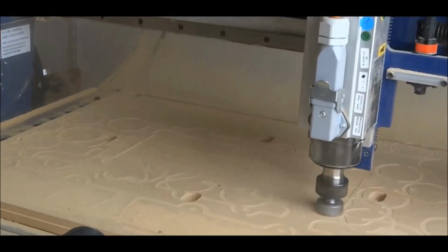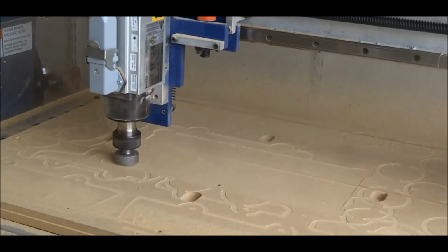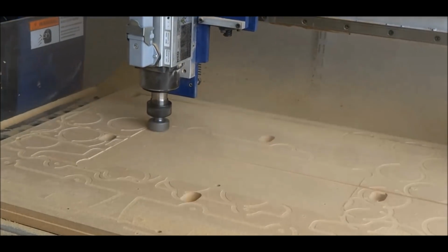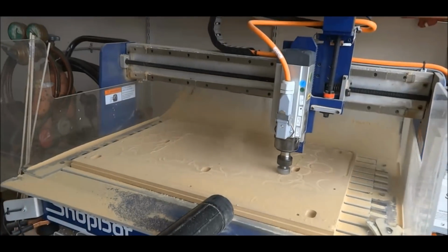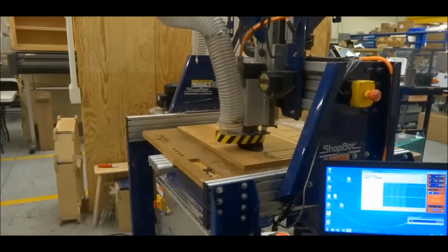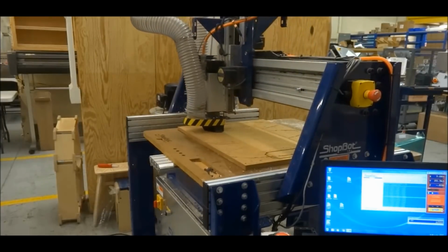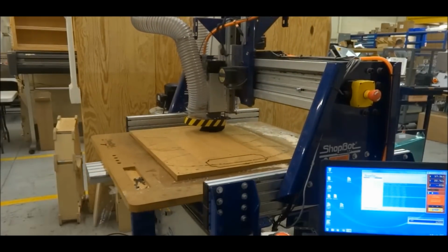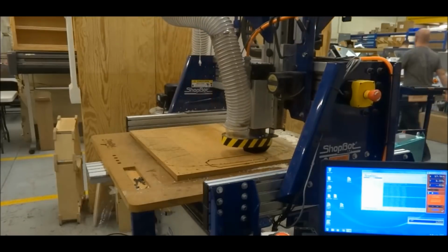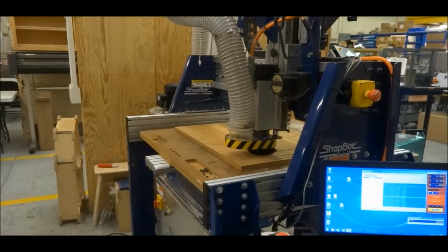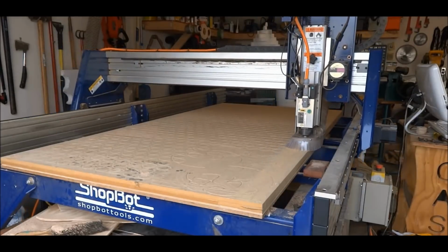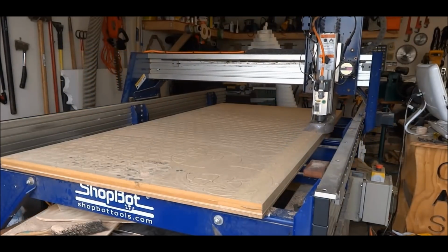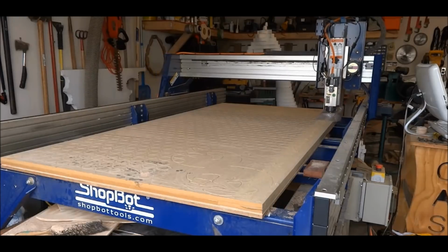There really is something to be said about having a nice flat table. It's really going to make a difference when you're working with a flat table that you have surfaced recently. When you first purchase your machine, you should definitely surface it. There's a surfacing routine built into the control software. You could also go into the Vectric software, your CAD, and design a rectangle the size of your table and mill it off.